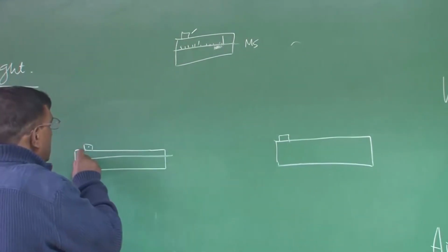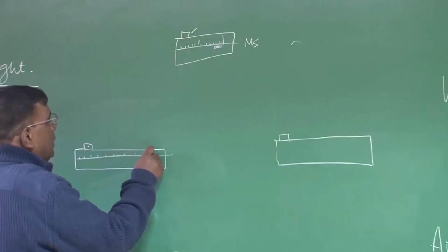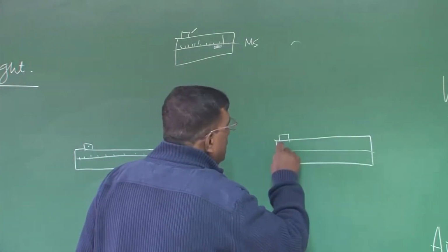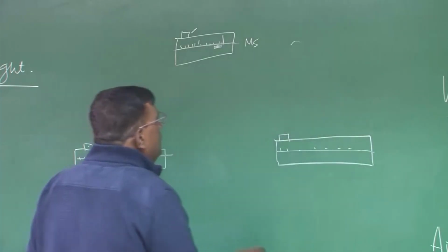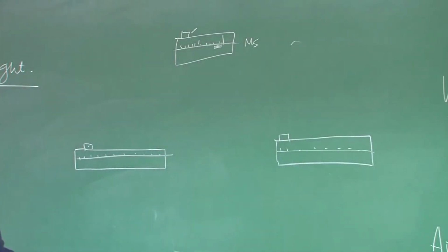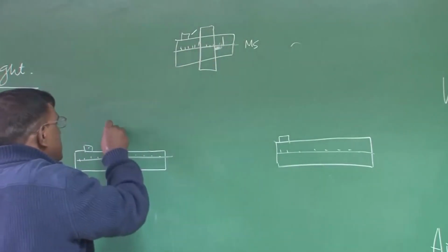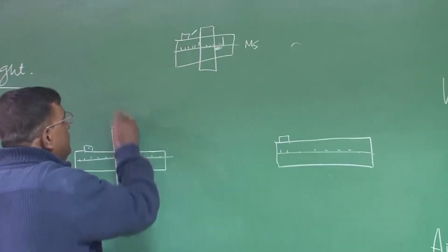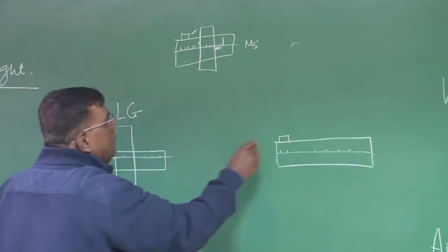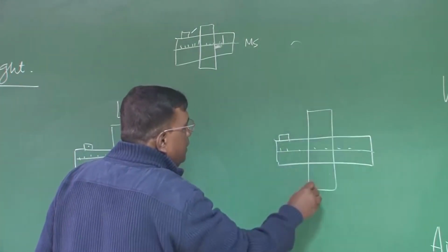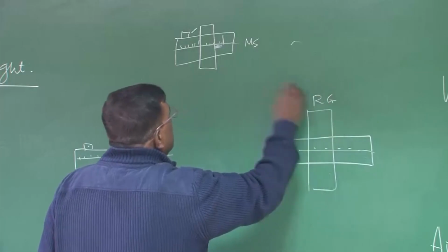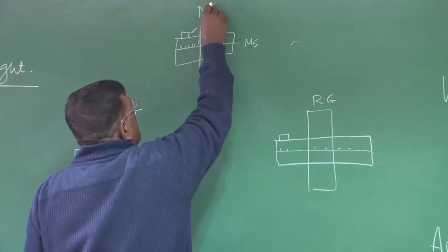Similarly here, similarly here. Right? And what happens? We drag the airplane and put the nose wheel on this balance, the left landing gear on this balance, LG is left landing gear, and the right landing gear on this balance. This is the nose landing gear here.